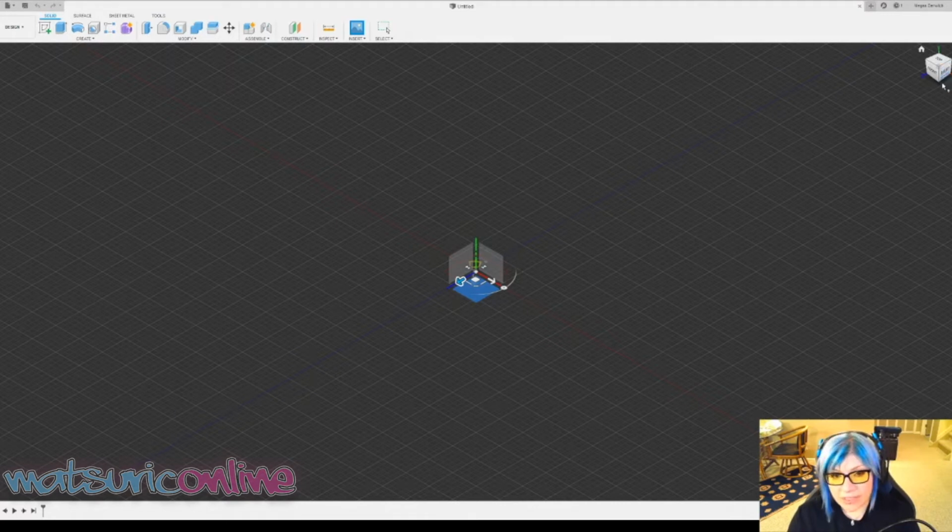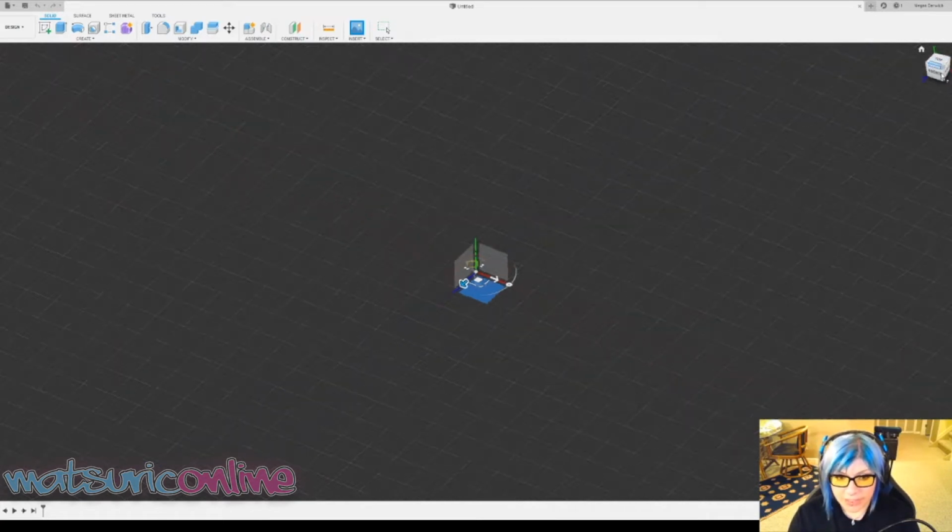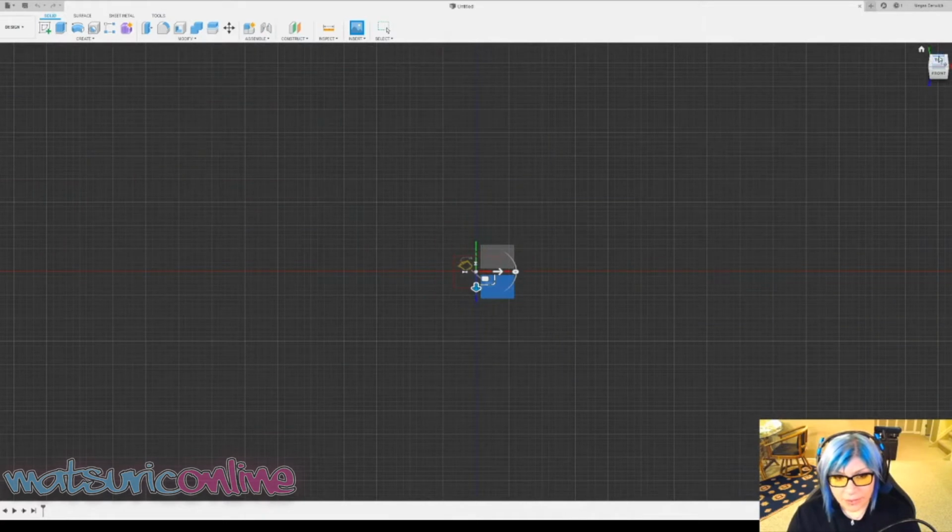So when I mention that, you can see your planes over here. This is your navigation cube, for lack of better words. It will give you your front, top, right, back, bottom features that you can just click, and you can click anywhere on these sides, and it will automatically rotate to that. And you can also see that's the Z-axis, that's the X-axis, and that's the Y-axis. This comes in handy when you have to do revolves. That becomes a really big thing.